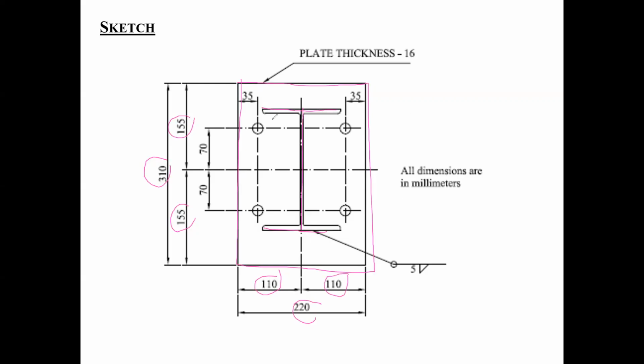So in other words, all the calculations you've done are based on the fact that you're assuming that the pressure underneath the plate is uniform. And that's only when the column is concentric. That's an assumption, okay? So that's number two. So you do not specify the column, because the column gets specified in a column schedule. You just show that the column is concentrically placed on the plate.